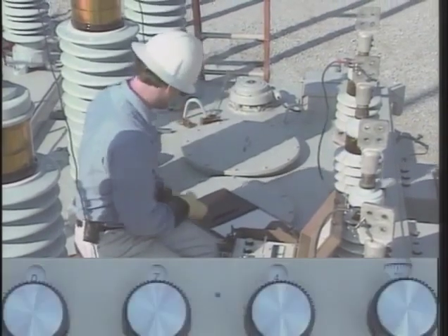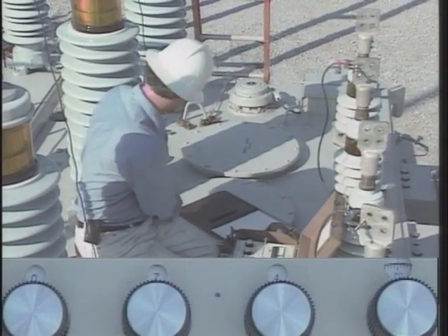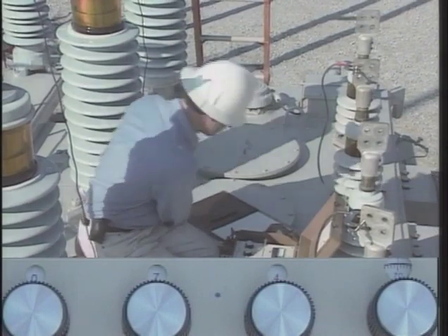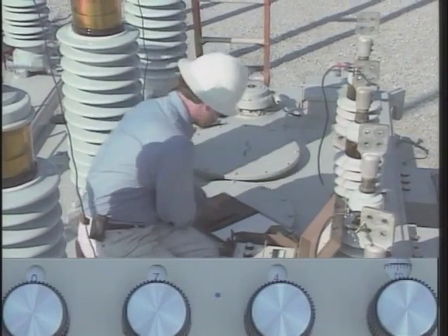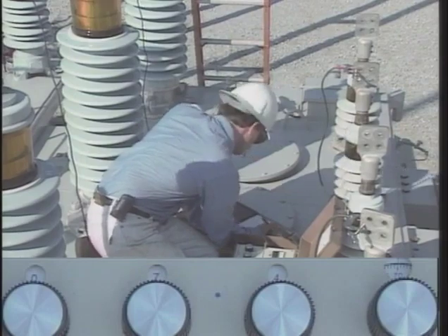The dial numbers are copied in sequence on the test form provided by your company for documenting turns ratio test results. This number over 1 is the turns ratio for the windings being tested on the power transformer. If the power transformer that you're testing is a tap-changing transformer, the test is repeated at different tap settings without changing the test connections.